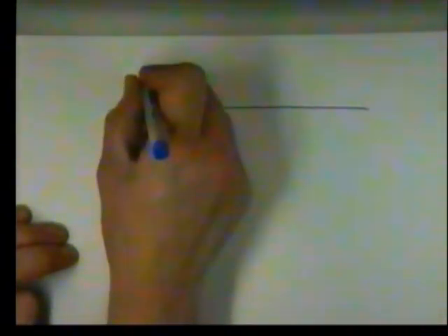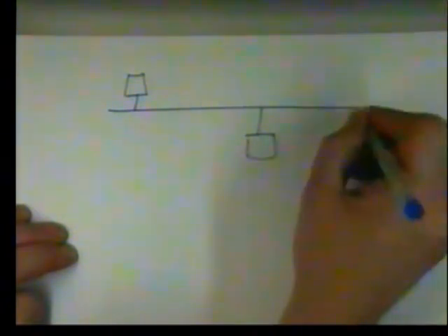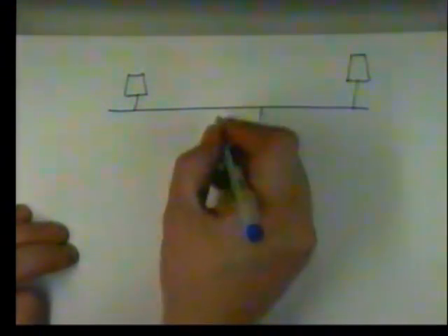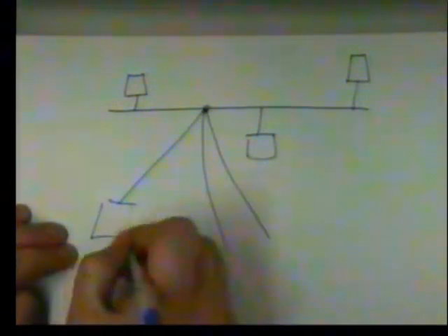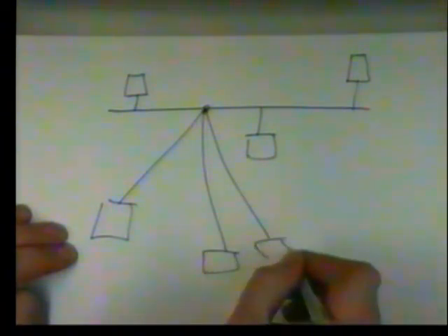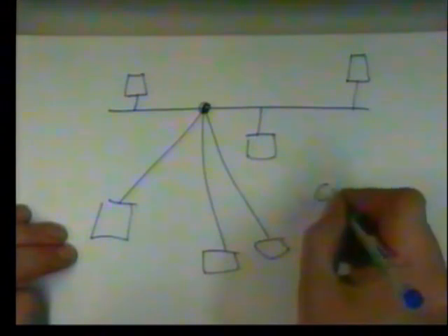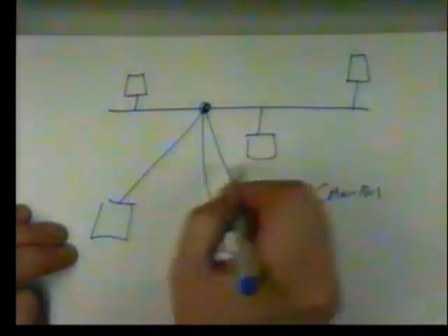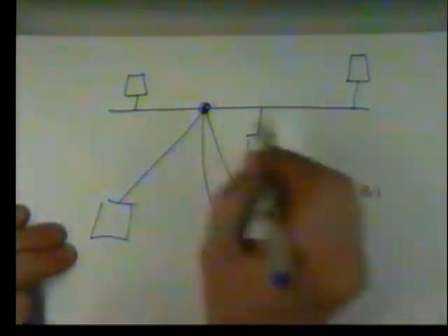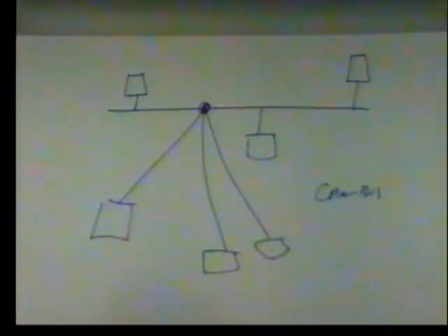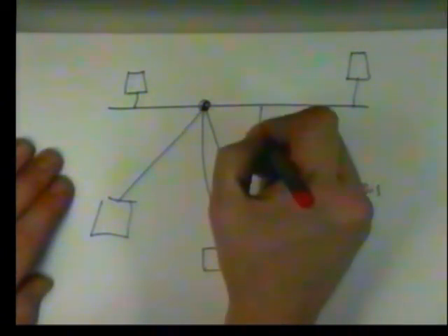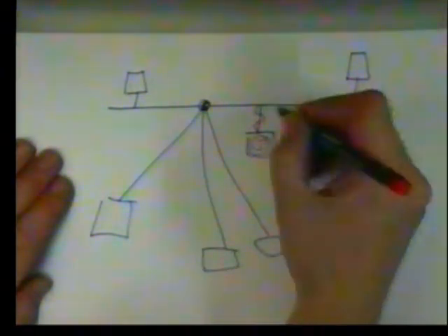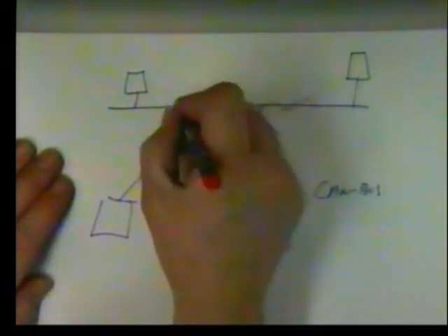So let's just remind ourselves, what is a bus? A bus is where you have a single high-speed cable and all the nodes sit on that. Alternatively, it can be a star arrangement with a single point going to many nodes coming back to a single central link. And in fact, most CAN bus LANs combine stars with buses. The key thing is that when a message is broadcast out onto the cable, everybody receives that information.